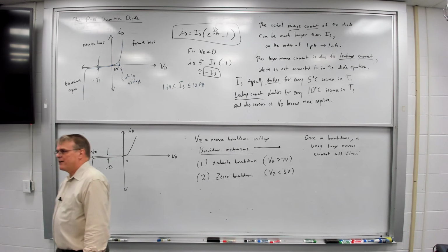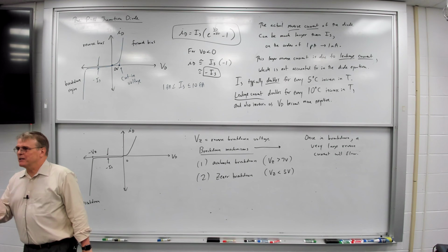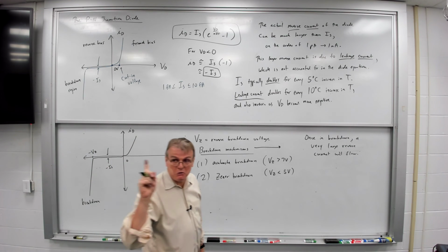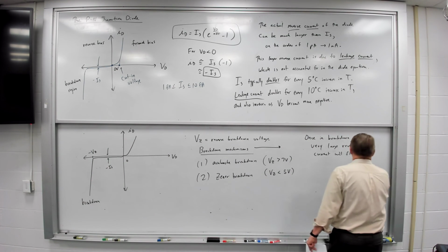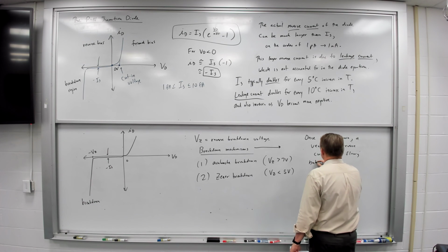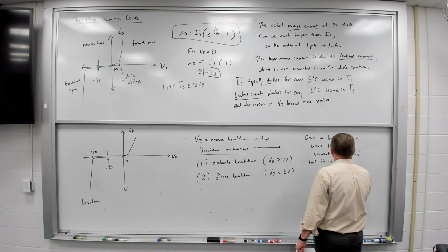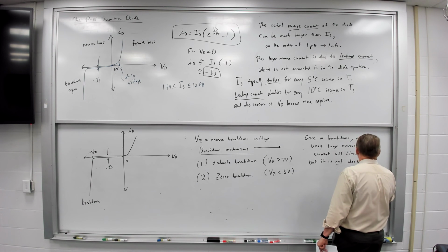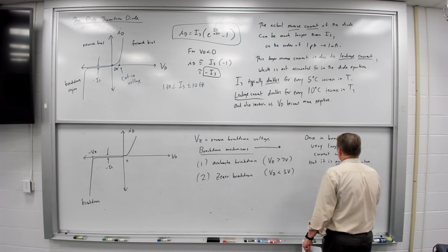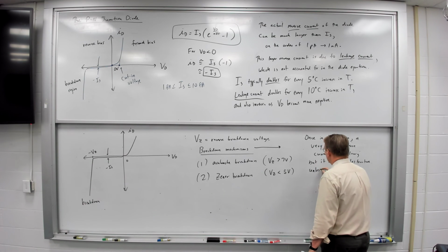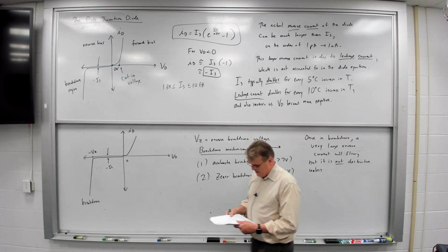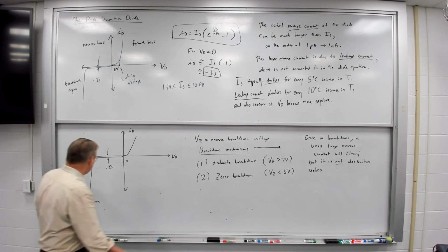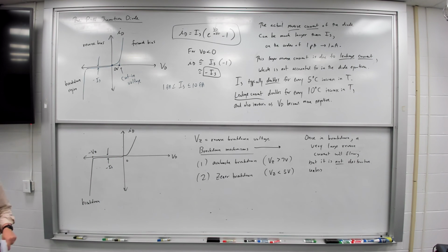Breakdown is not destructive unless the magnitude of VZ times ID exceeds the power rating for the diode.